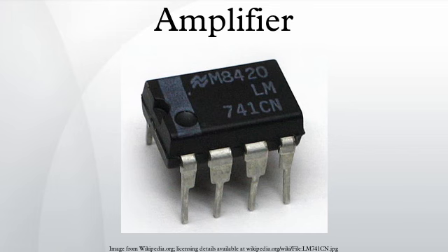The Class E amplifier takes the finite on resistance into account and tries to make the current touch the bottom at zero. This means that the voltage and the current at the transistor are symmetric with respect to time. The Fourier transform allows an elegant formulation to generate the complicated LC networks and says that the first harmonic is passed in the load, all even harmonics are shorted and all higher odd harmonics are open. Class E uses a significant amount of second harmonic voltage.